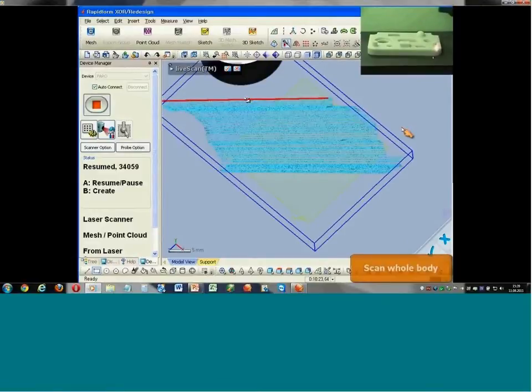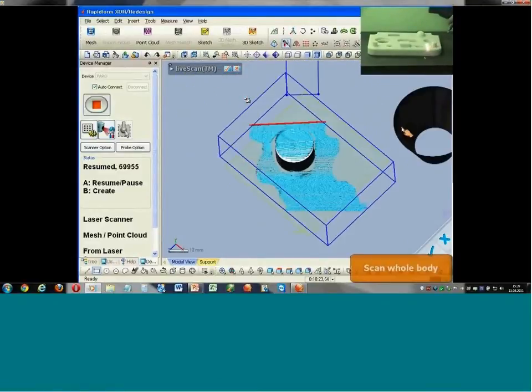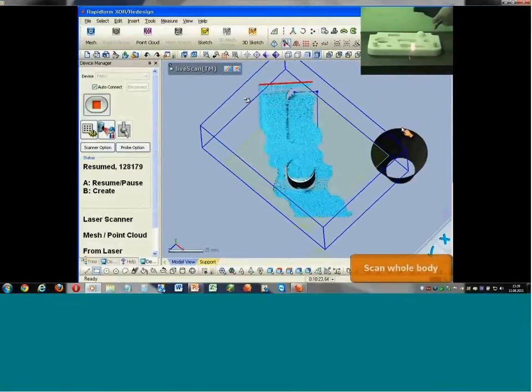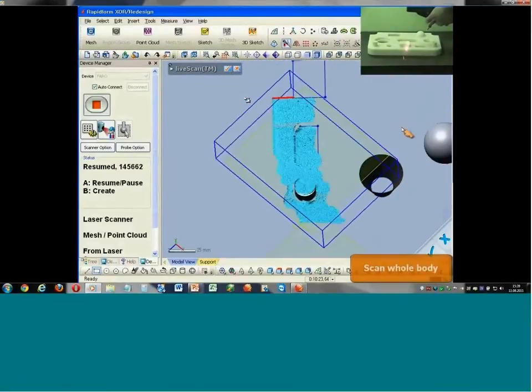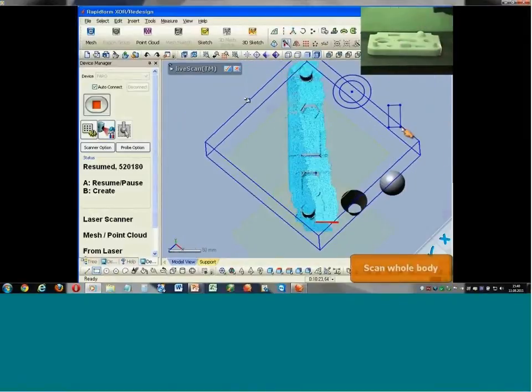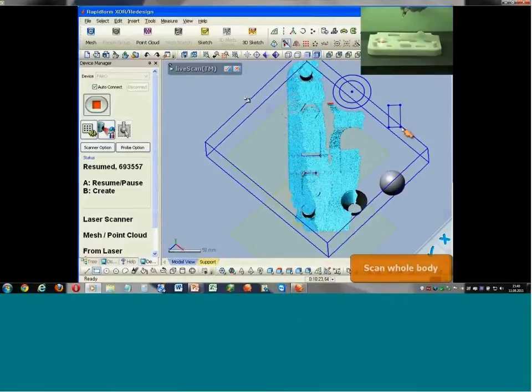And we can seamlessly switch to scanning and combine every feature which we created. So using the 2D sketching and probe some circles, for example, and then later on set the concentricity between the circles and get some dimension from the circles. Or create your base solid from the scan data and then use the sketches from the circles and use the bodies which you probed before and combine them with the Boolean operation.